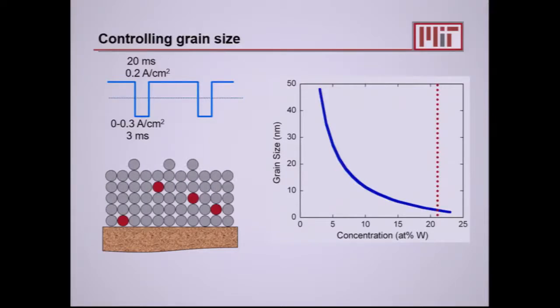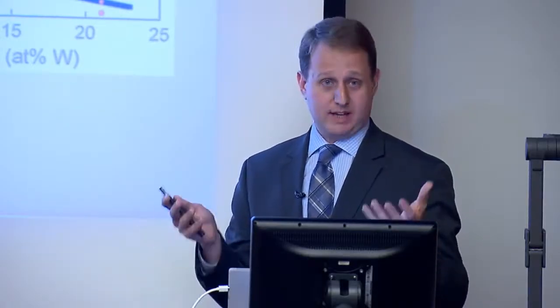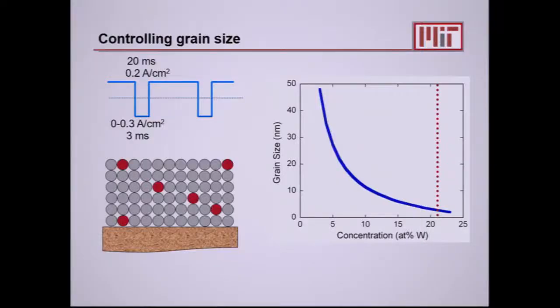And this over-trivializes it because, of course, these atoms are all moving around, and they're assembling. And in fact, they assemble into nanocrystalline structures. And I'll show you that. And how did he find 20 milliseconds? Is that in the literature? No, you can calculate it. So you know the plating rate. In fact, it's a simple calculation. You know how many microns per hour, scale that down to monolayer thickness, and it's a 20 millisecond time.